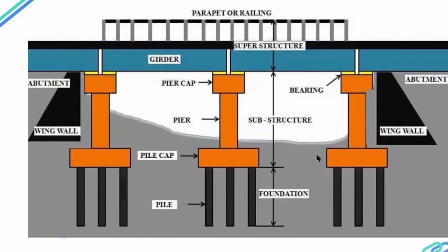In metro viaducts, typically we are going ahead with pre-stress pier caps because they are precast, they are launched onto the piers, and then they are pre-stressed. So the construction becomes quick, and they are very slender. They blend aesthetically into the landscape of the city. For those of you who would have seen the airport line of the Delhi Metro, they must be aware of these slender pier caps, and they look very beautiful, and they add to the aesthetics of the city.